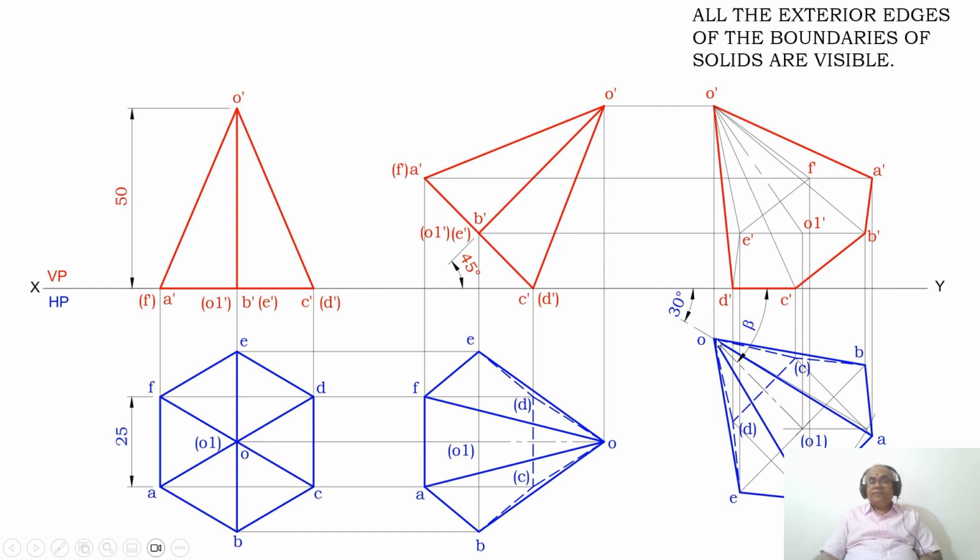So to do that, first I will consider any point, and then from there I will draw a horizontal line. Then with reference to that horizontal line, by using the protractor, you measure an angle of 30 degrees and you draw an inclined line.